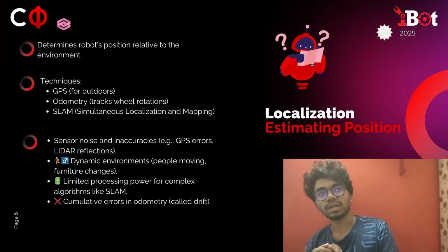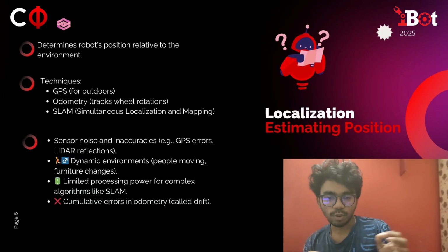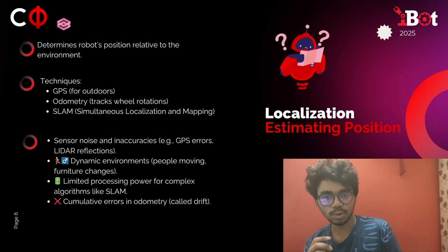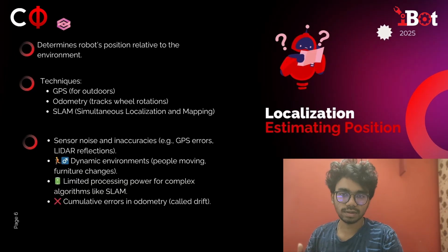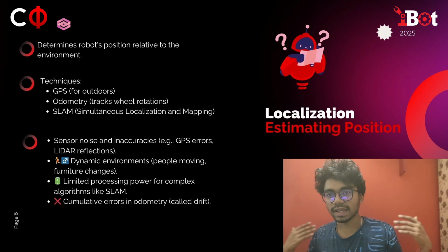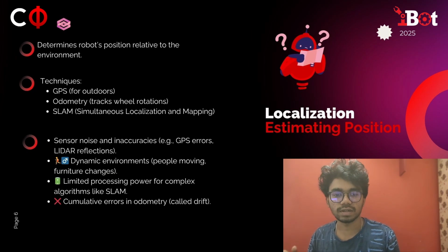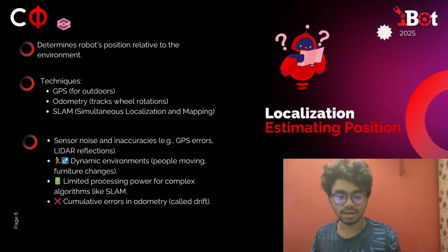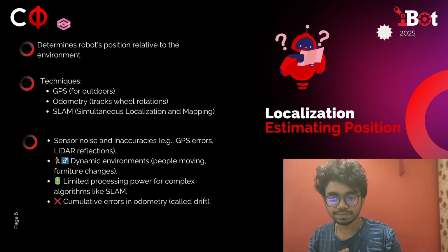And the fourth point is cumulative errors. Even if these errors are small, over a long time as the robot moves they stack up on each other and may lead to a higher and higher amount of error. These problems will be mostly solved by good path planning and good control overall.